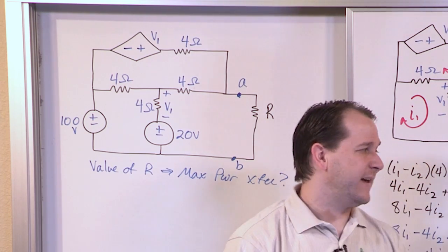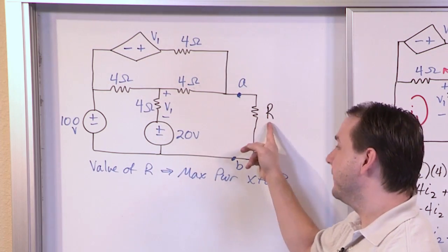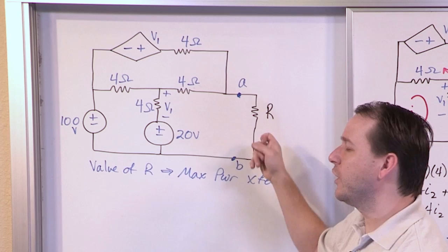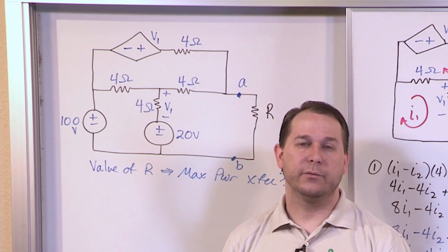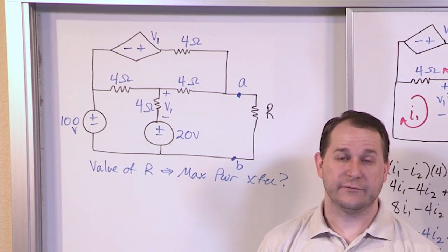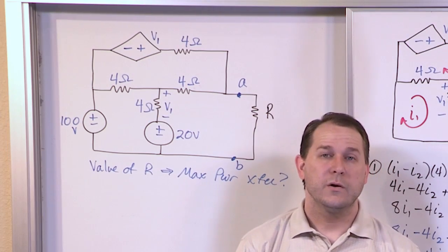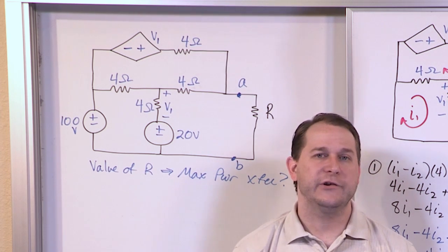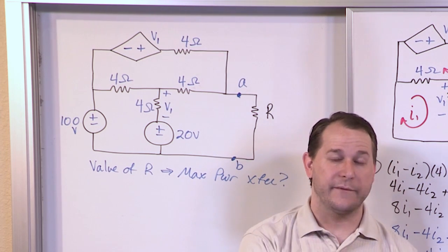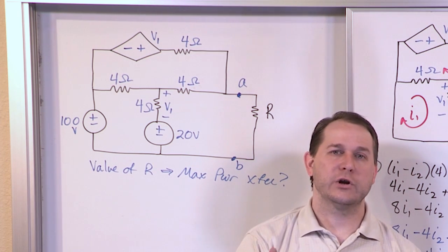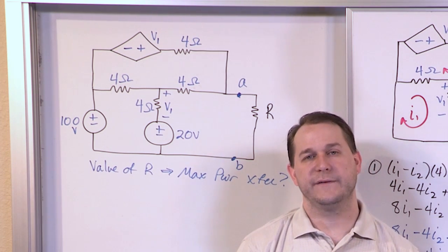way you really should do it is take 3 ohms, replace this unknown with 3 ohms, and solve the circuit again, figure out what current's actually flowing through that resistance. And then once you figure that out, then I squared R is the power delivered to that resistor. Or once you have the Thevenin voltage calculated, you could use the equation I gave you from the very last section right before this one, where the maximum power delivered is V Thevenin squared over 4 times the load resistance.